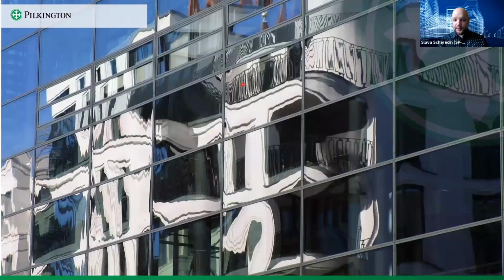Here is an example of the thing done wrong, when the facade has an optical distortion perpendicular. So the picture is not that pretty as on the previous one. Okay, so proper design combined with proper tempering. In order to avoid this, use thicker glass, go for a good processor.